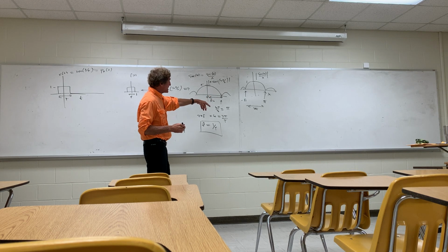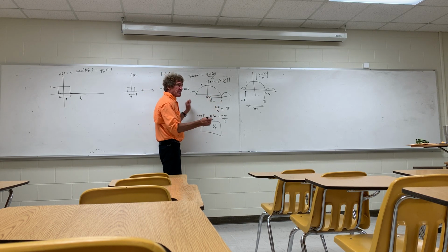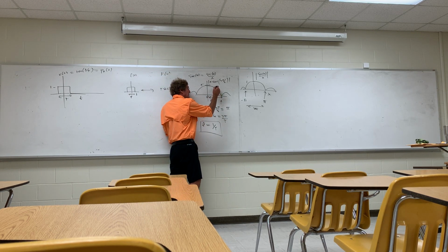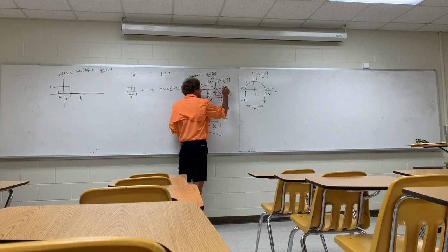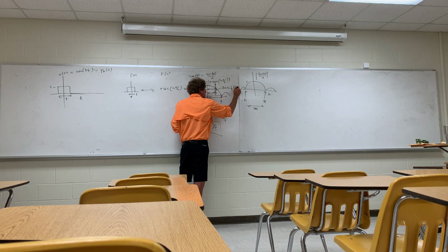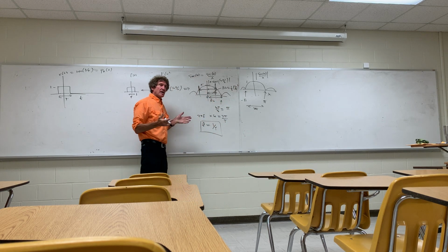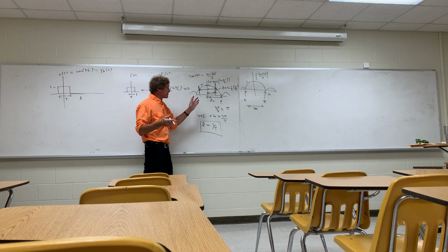Now the truth is, that's an absolute 0. The half power point would be about at this value, or at 1 over tau divided by 2, or at 0.5. So what he's really talking about in his book is this as the bandwidth, but it will only be from 0 out. So he's saying the bandwidth in his book is given as 1/2 times this cutoff frequency, which is 1 over tau. Can y'all follow me on that? That's the reason he does it.